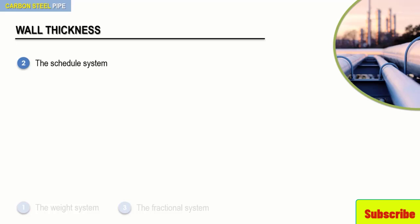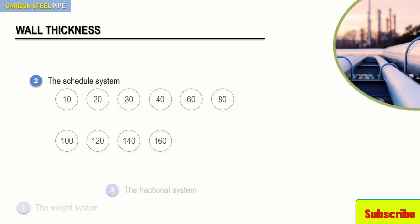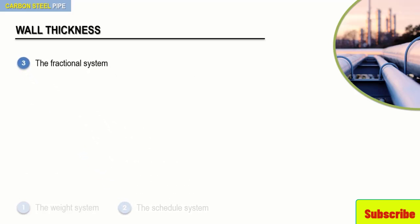In this system, pipe, depending on the diameter, is manufactured in the following schedules. Now, don't worry right now if these numbers are not clear for you. We will come back to them later in more detail. The third system of categorizing wall thickness is the fractional system. This last system consists simply in measuring the thickness of a pipe in either a fractional or decimal value.